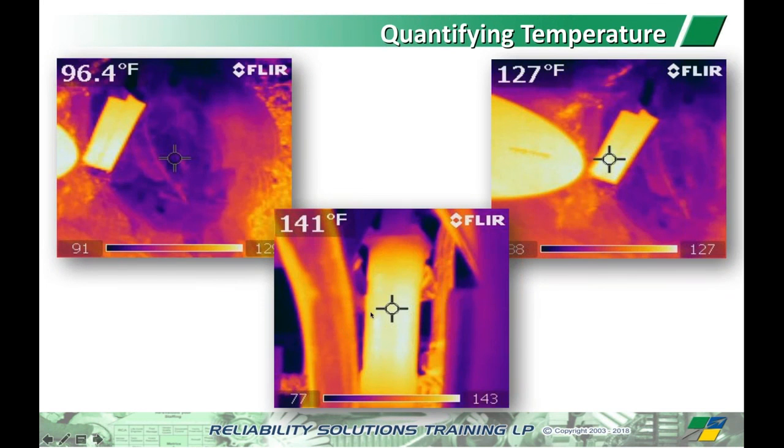A couple of little fuzzy infrared images here. Again, looking at a big hydraulic system, you can see where the heat flow goes. I use infrared to validate that my filters are operating correctly. You can definitely see if a filter's in bypass and plugged, because the bowl of the filter will be relatively cool compared to the head, where it's all going across the head. So many uses for this. And with the cost of the imaging tools coming down so far to where they're pretty affordable, I don't know why we would not have something like this.